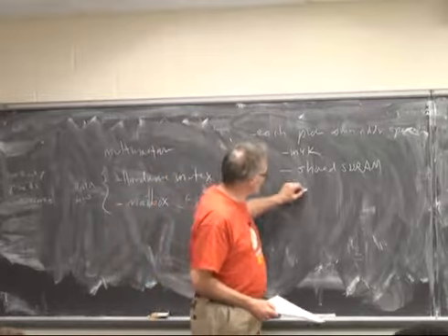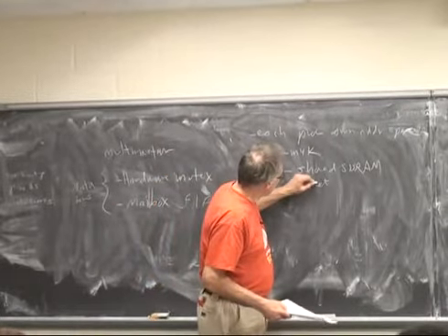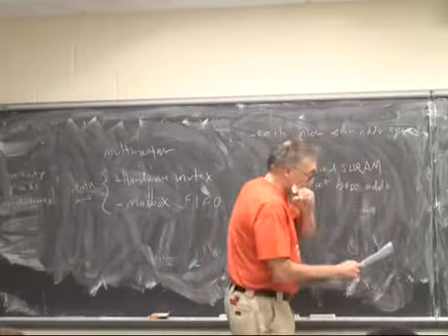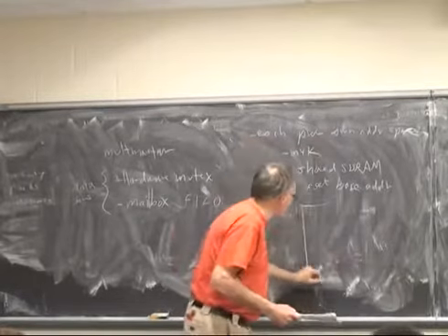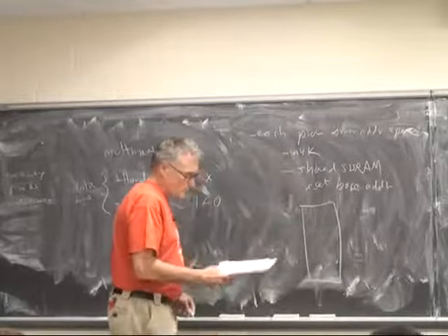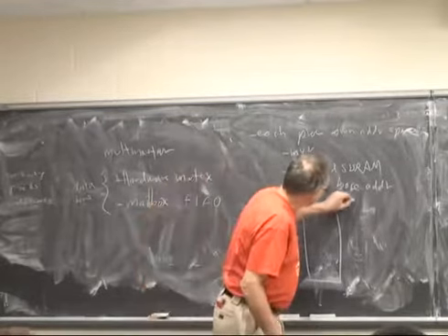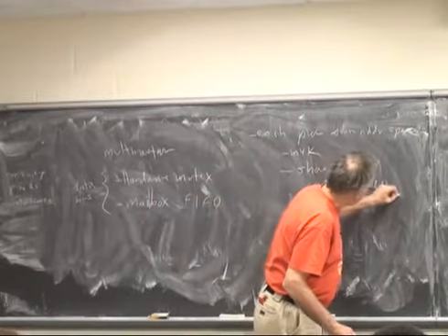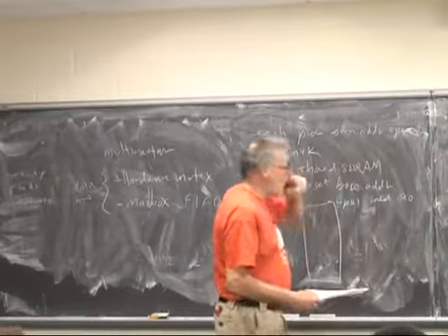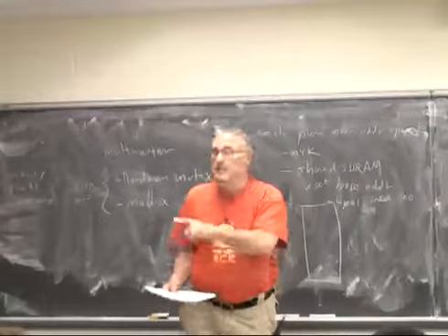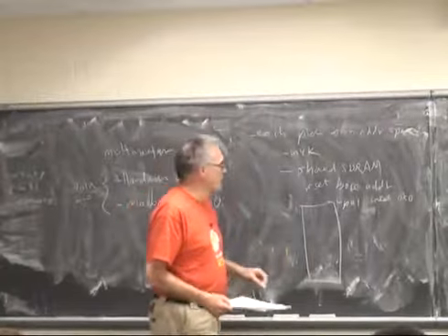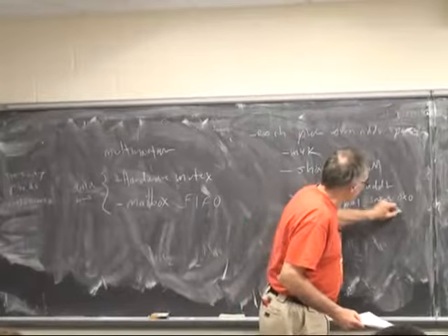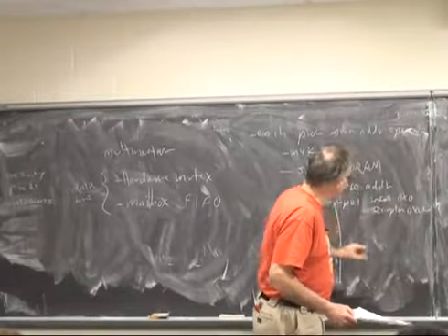So the reset vector now becomes the base address. So, for instance, if you had 3 processors, CPU 1 might have a reset of 0x0, which implies that its exception vector is going to be exactly hex 20 higher. So it would be 0x20.